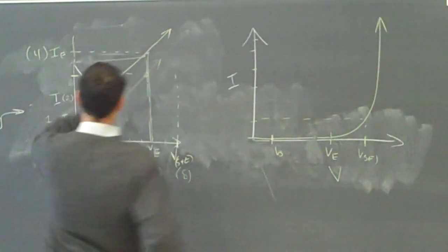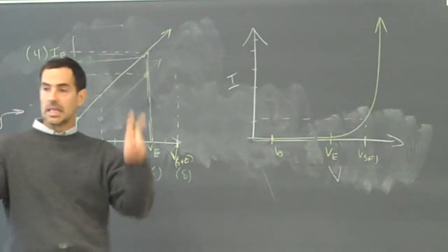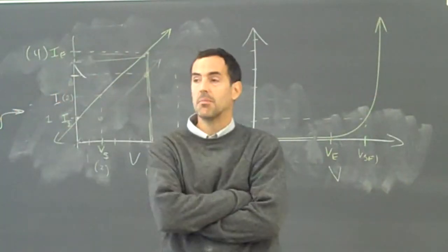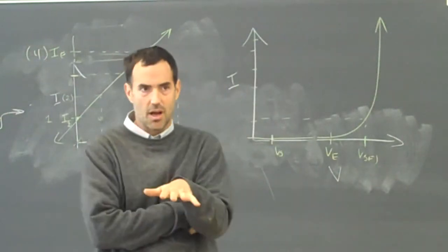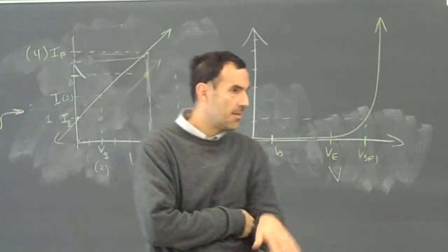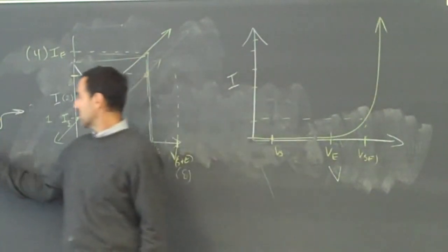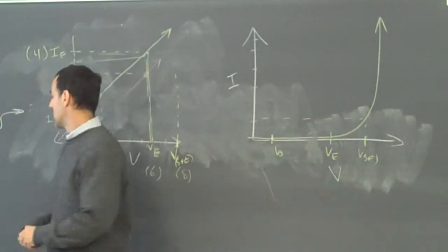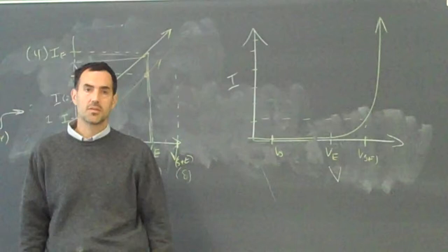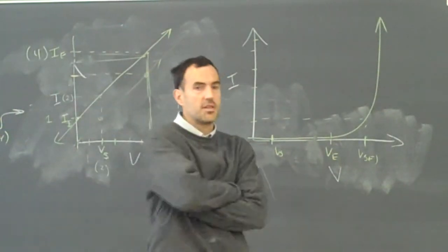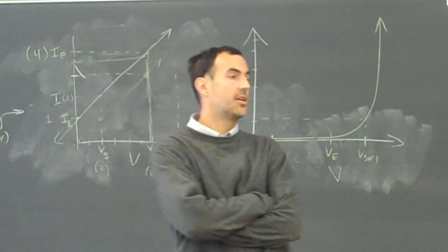So by taking this curve and shifting it up, I make it no longer linear in what we mean by that term. So it's a little different than what we just mean by a straight line. Linear doesn't mean straight line. It means that these effects add together. Basically, this principle of superposition is valid for linear systems. The resistor is a linear component. The diode is not. The op-amp behaves like a linear component.